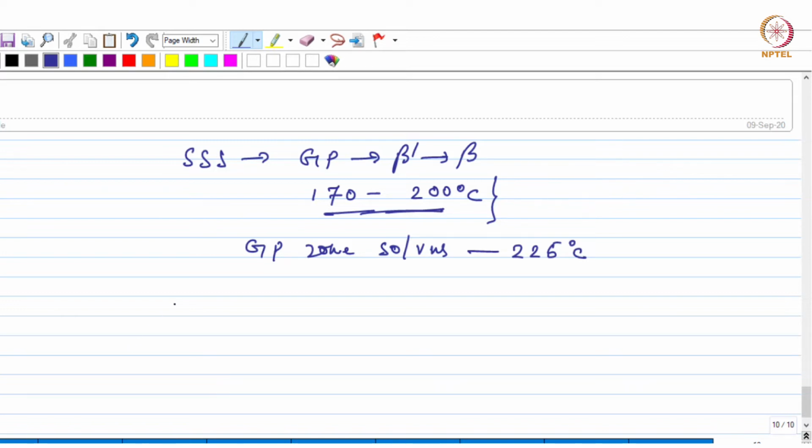And this precipitate will form for a particular ratio between magnesium and silicon, which is around 1.73:1. In some cases there may be a little excess silicon, and that will in fact give rise to higher strength but low corrosion resistance.